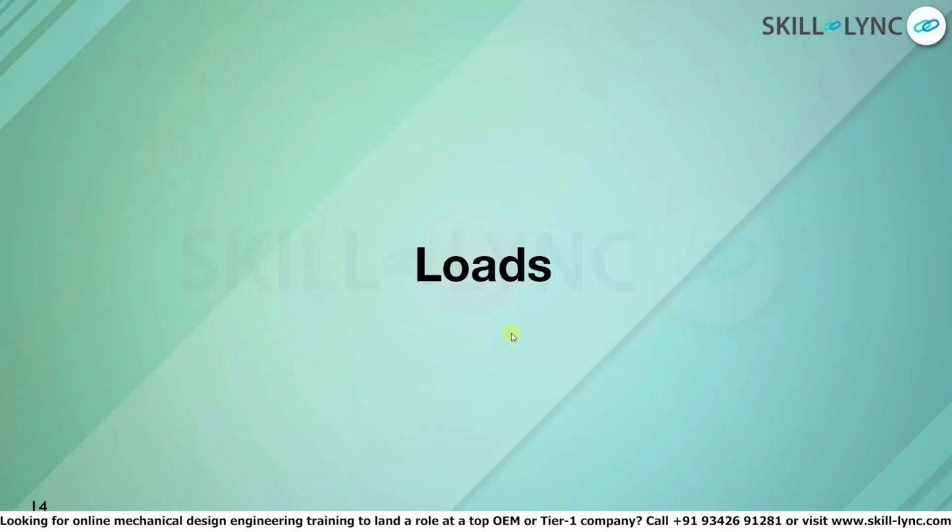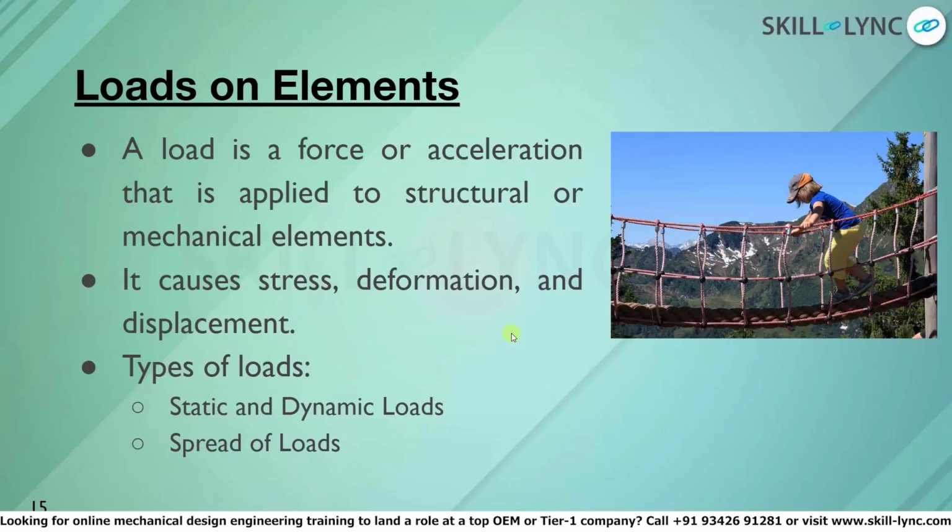Next, we look at loads. What is a load? A load is a force or acceleration that is applied to a structural or mechanical element. It will cause stress, which causes deformation and displacement on the object. In this figure, we can see a rope bridge as the person walks over it. So, by definition, it will bend or deform.